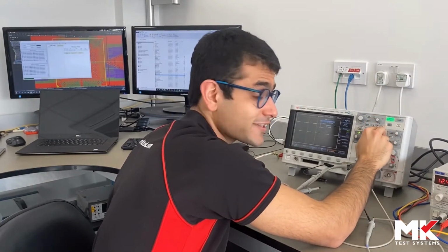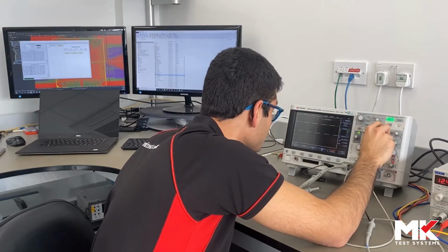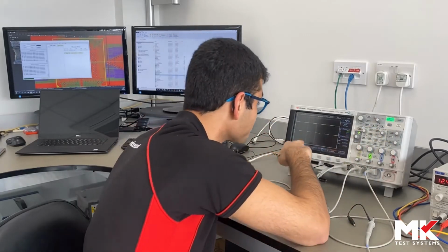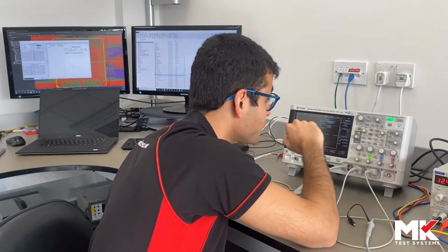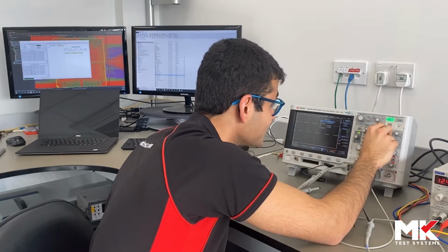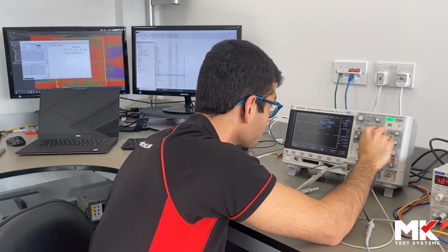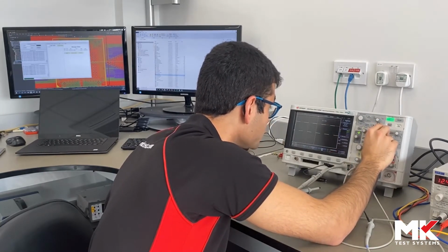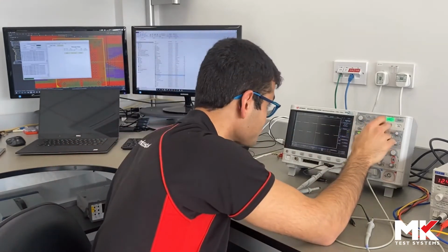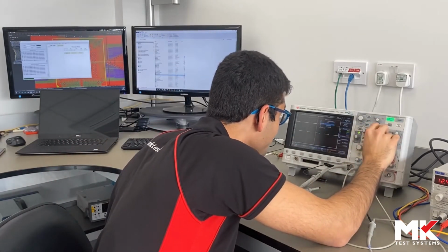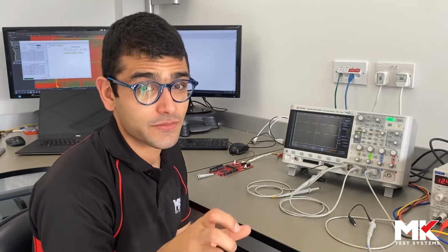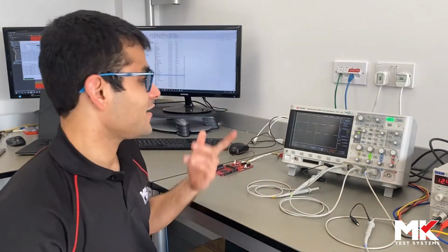First thing I'm going to do, I'm going to select X1 and choose the first falling edge of the wave. Here we go. Then repress the adjuster, select X2, and move it to the end of the wave in order to measure the wave period, and from the period I'm going to determine the frequency. Here we go, it's set up. Then after setting X1 and X2, always remember to link them together so you don't change the displacement between them.